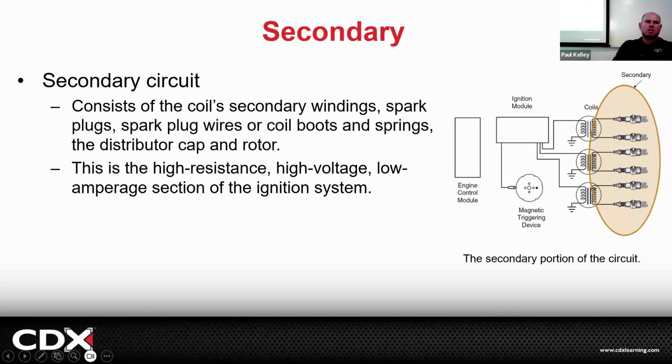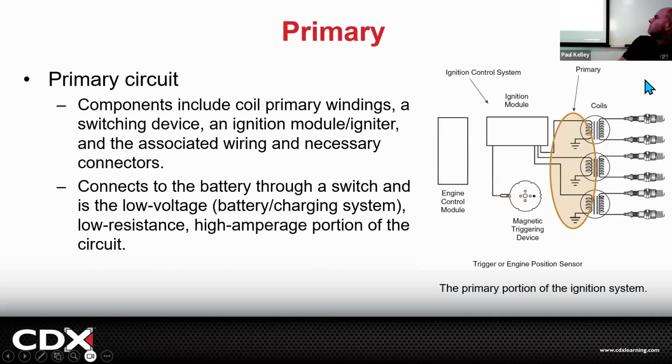Remember that car I told you about? Customer called and they had a primary ignition circuit code. Do you understand now? I was saying, forget the spark plug, don't bring the spark plug up again. It's a primary ignition circuit code. She's very fixated on the secondary spark plug. If it's a primary, that means it's between here and here. We're not worried about the secondary side. Get what I'm saying? Got to have the primary working to even have the secondary trying to work.